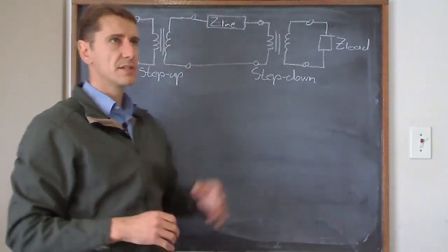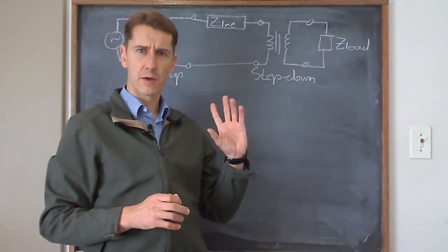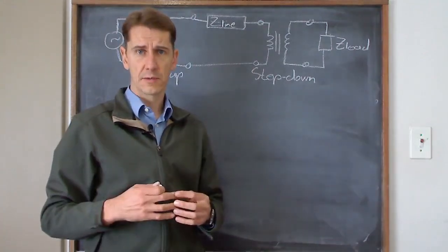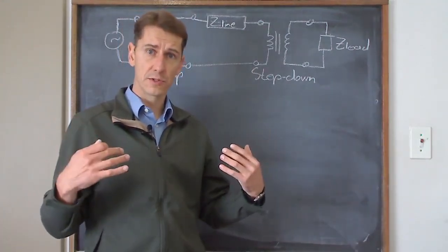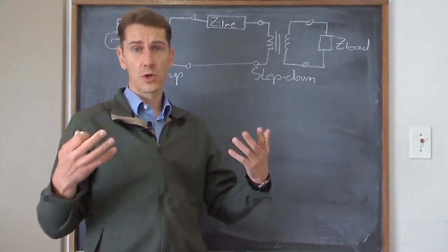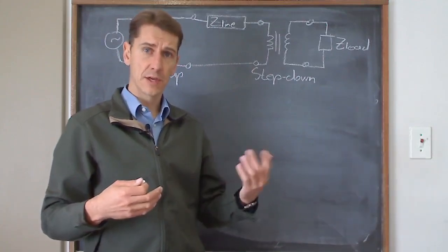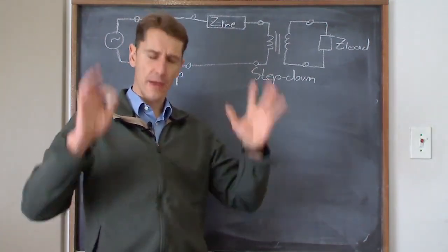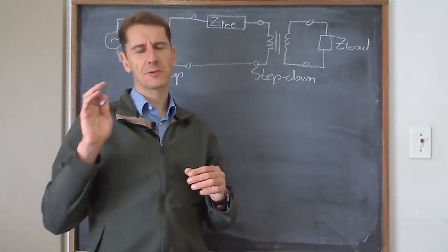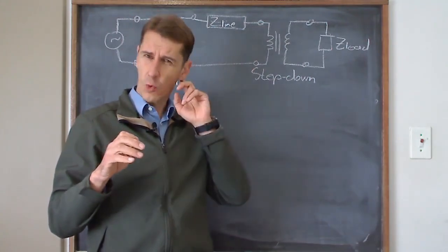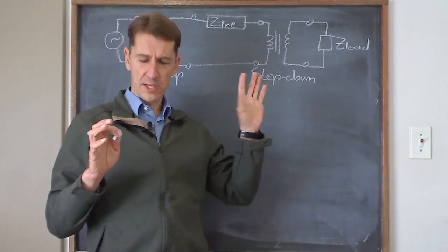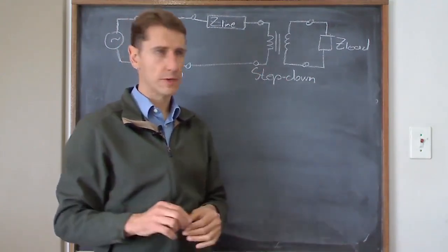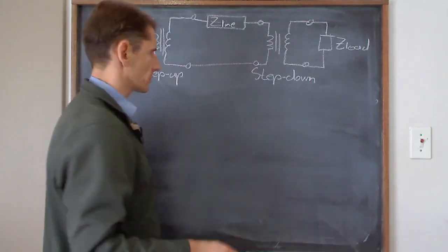Now, typically 765 is an exception. Usually, the longer distance is around 400,000 volts. And when it gets into Tshwane, for instance, the substations are sitting at 132,000 volts. That goes down to 11 or 22,000 volts. And the substations in residential areas take it from 11,000 to 400 volts. So next time you walk past those green substation boxes next to the road, most of them you'll see 11 kV to 400 volts. Not 400 kV, 400 volts.